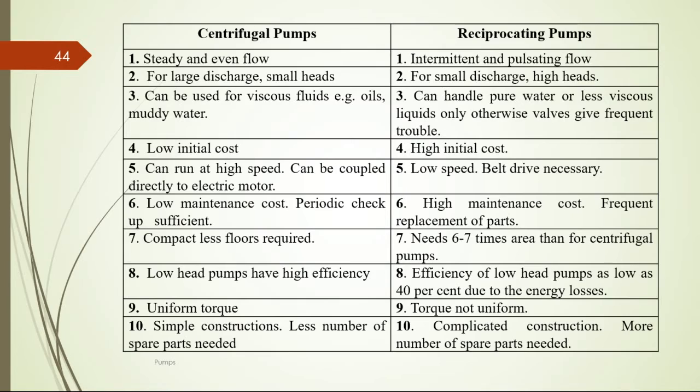Centrifugal pumps have low initial cost, whereas reciprocating pumps have high initial cost. Centrifugal pumps can run at high speed and can be coupled directly to the electric motor, whereas reciprocating pumps are low speed and a belt driven arrangement is necessary.